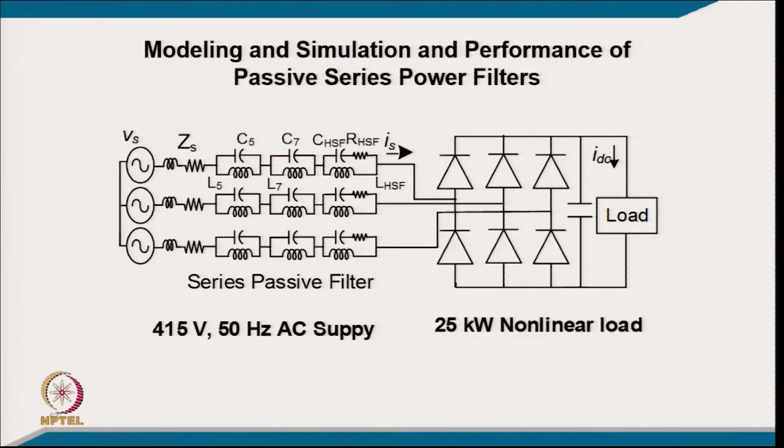It is an adjustable speed AC drive consisting of either an induction motor, or a permanent magnet brushless DC motor, or any other motor fed from constant voltage. That is the total system, but we are only considering the input part, which is the only interface to the grid. If there is no passive filter, it sucks unlimited harmonics, depending upon the time constant of the capacitor along with the load.